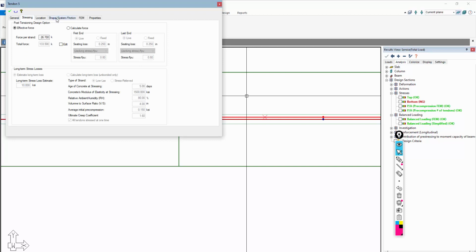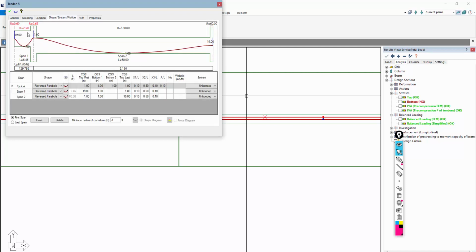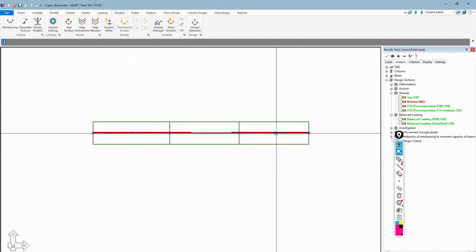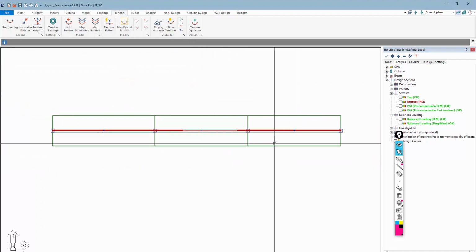We have our stressing setting, and then we can manipulate, let's say this tail, we'll say it's a cantilever down, and we're going to drop that down, let's say 3 inches, and raise that up 3 inches. Then over here we're saying that's 9 inches. So there's one add tendon. We have add tendon on this left side, right side, and then we're going to do one right in the middle.